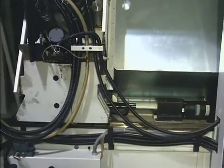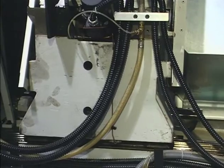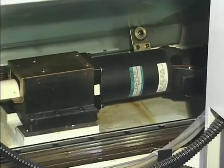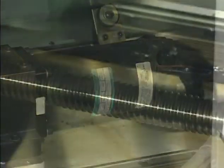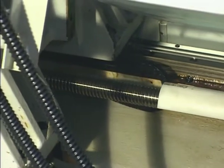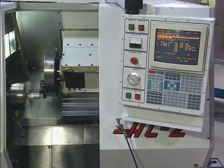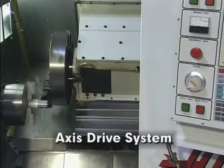Each axis consists of a mechanical component, such as a machine slide that moves, a servo drive motor to supply power for the movement, and a ball screw that transfers the power from the servo drive motor to the mechanical component. These components, along with the computer numerical control functions that direct them, are called an axis drive system.